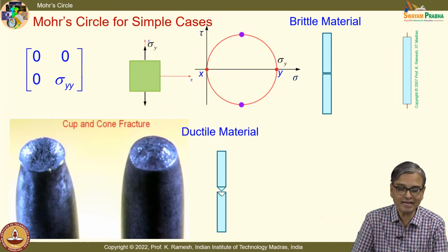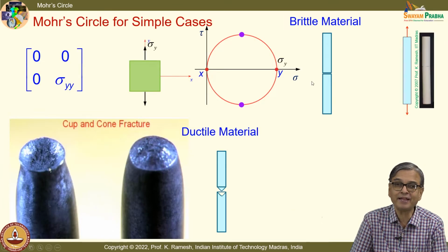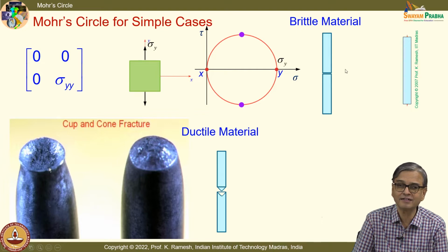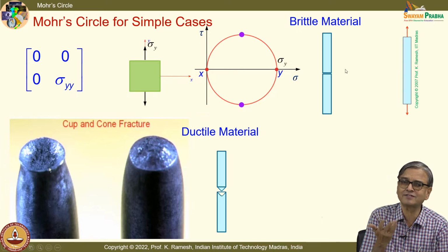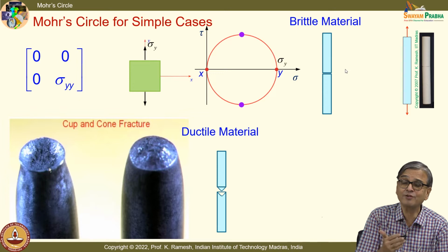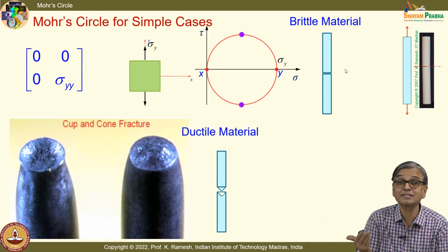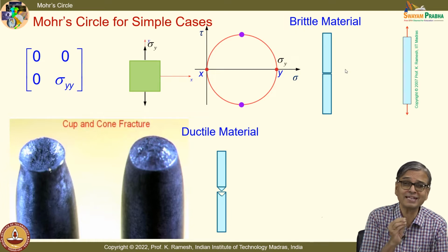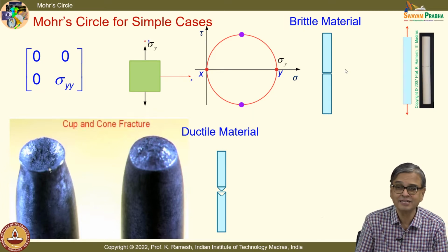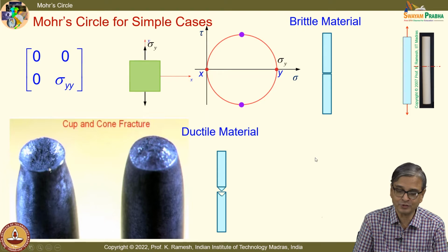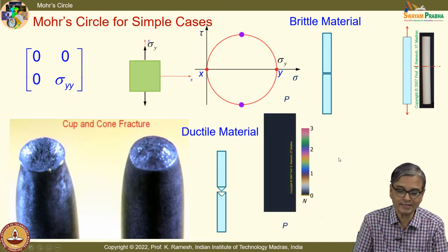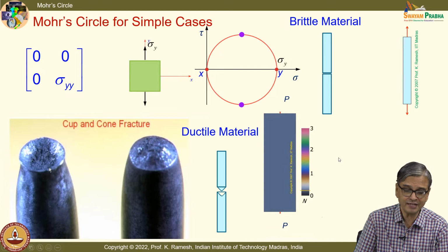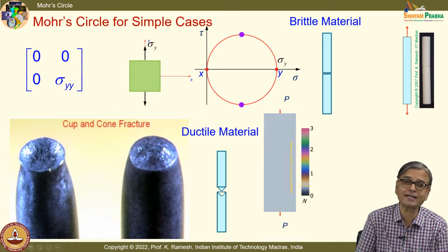If I have a plane like this, which is the y plane, on which I will have the maximum normal stress. But suppose I have this surface, that is a free surface, you will have the stress vector as 0. But there you are looking at a plane which is the x plane. So, you should know that will take some time. Once you keep discussing these issues, you will be in a position to appreciate how to look at the planes. And I said even the photoelastic fringe pattern is also a graphical representation.